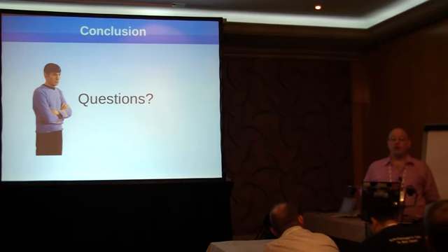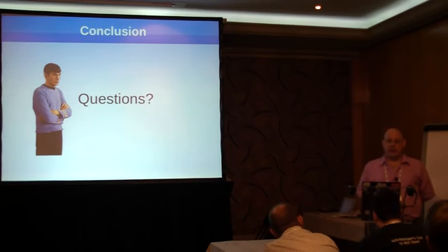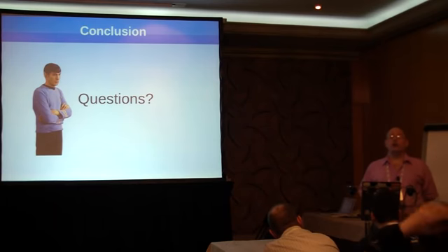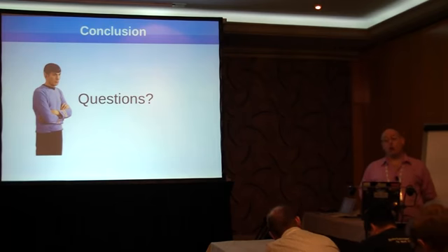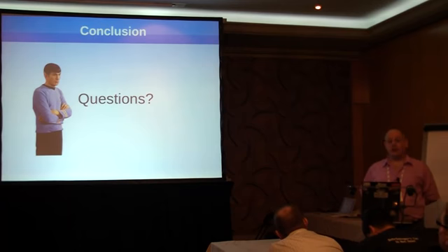Most of the time, I use either one or two things. One, I make sure that the EEPROM is actually on a breakout board that I can unplug and then plug into another identical device. Or there are a wide range of USB to GPIO type devices such as the FTDI FT2232, which actually has USB to I2C on board, and you can use this through libUSB, and there's quite an extensive range of libraries that allow you to do that. Once you've set it up with the USB to I2C device, all your standard tools like i2cdump and i2cdetect work perfectly fine.